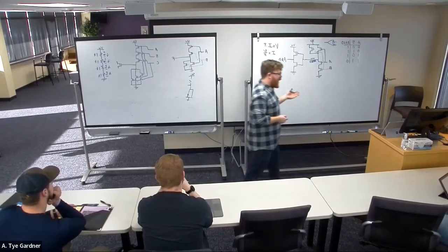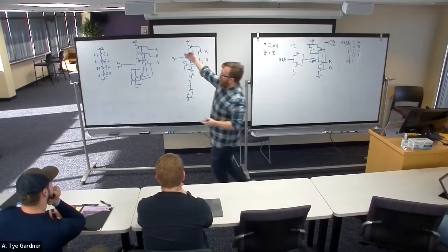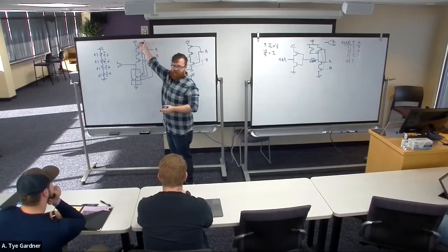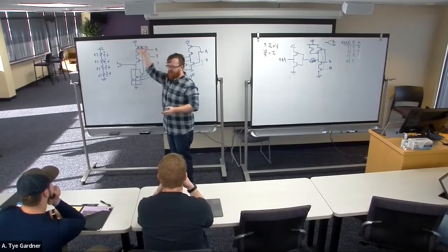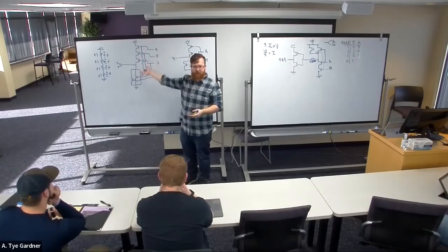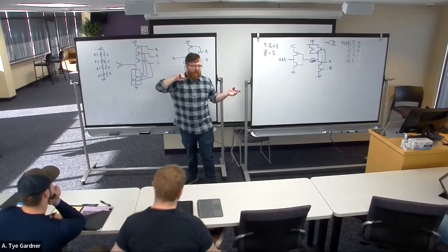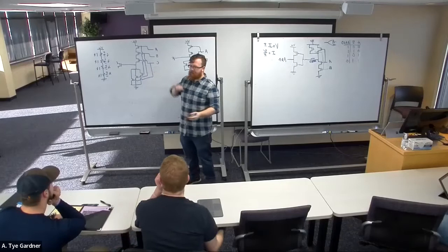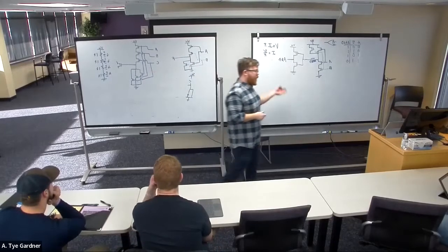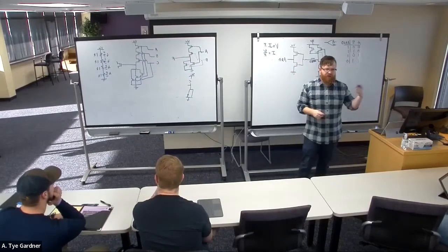And so we have this trade-off between the voltage overhead that we have, 5 volts, and well, how small the devices get, right? So if I bring 5 volts down to 1.8 volts, 1.8 volts is smaller than 5 volts. That usually means less power, but maybe it means I can stack fewer devices, right? And you'll go into kind of these design trade-offs and device physics later.